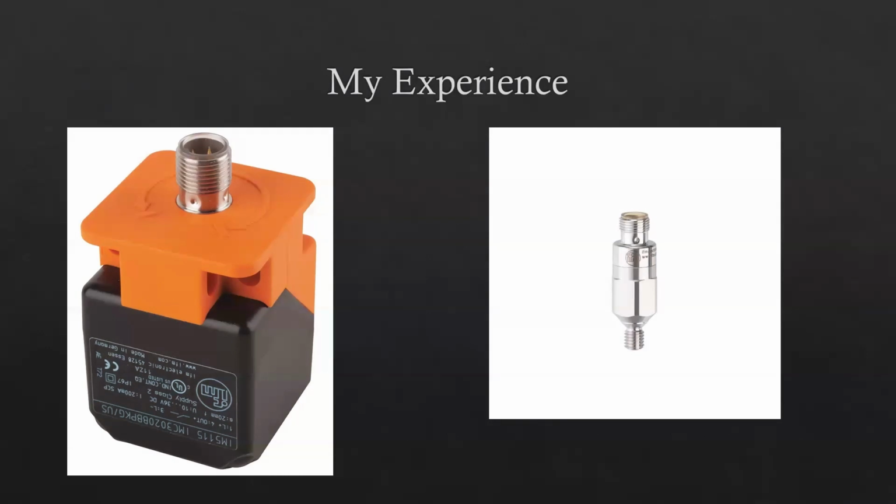So I used an IoT gateway essentially to hook up three different inductive sensors to different doors on the CNC machine. You could track optimal cycle times using just a timer when the door was open and closed at maximum efficiency. You take the mean of that value and implement that as the ideal cycle time. And then we'll use these inductive sensors to determine whether or not doors are open or closed and why they're open or closed, whether it be for maintenance, breakdown, or just inefficient cycle time.